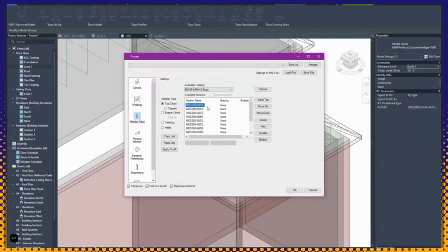And if that size doesn't work for all members, if you just hit analyze, it's actually if it fails, you can go and design your truss, and it will basically go down the list and see which members will work for which portions of the truss. Okay. And if I want a capped member, if I check this on, it will only show me the 2 options that we have for capped members. If I uncheck that, then it shows me everything that we have kept in this list.